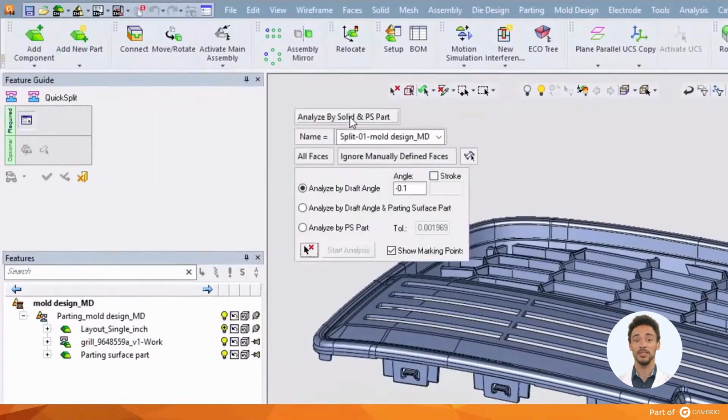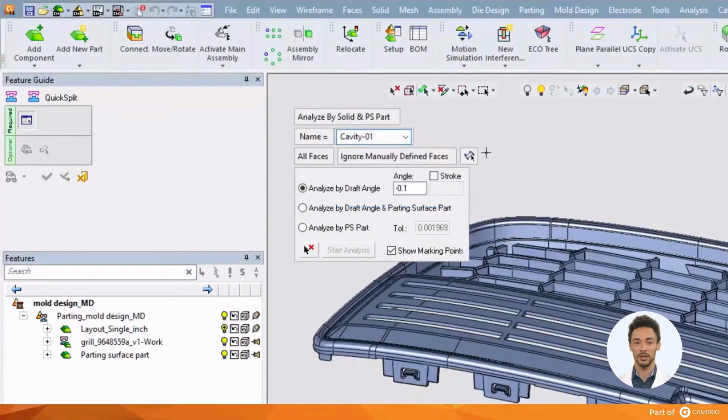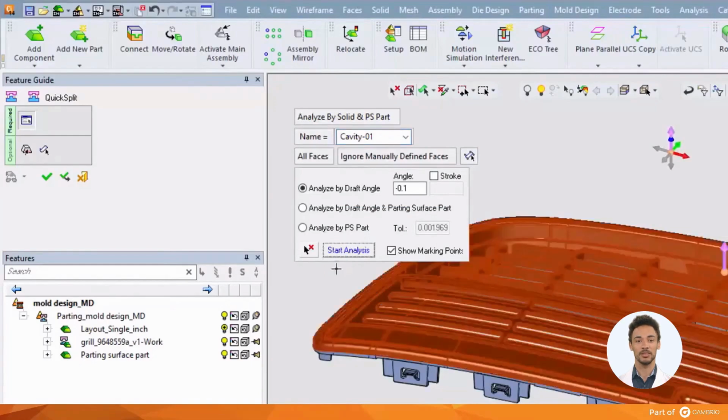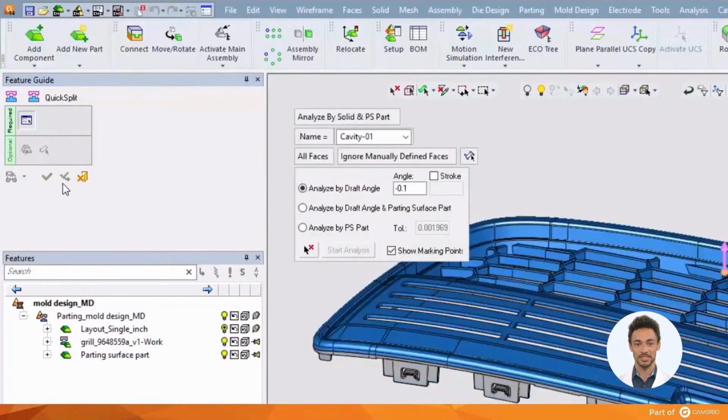Click the New Direction button to select our first pole direction. Select a name. Then pick a face that we know lies within that pole direction. Cimatron selects the active Z-positive axis for the pole direction, but we could pick another if we wanted. Now all the faces that it sees in that direction are placed on the cavity.